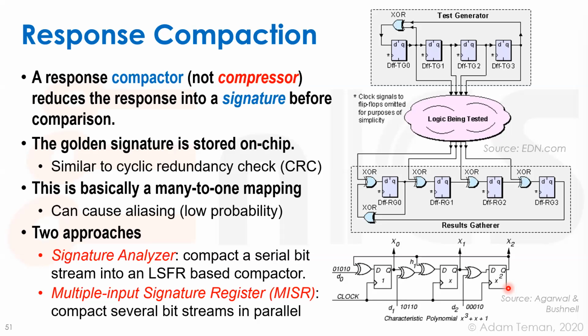Again, we run this before making our chip or in simulation. We see, if we put a certain seed inside the LFSR, we know what the output will be for our set of tests. So all we have to do is store that output and check that the state of the MISR at the end of the run is the same as what we stored. And we don't have to store very much, so it's really good. Okay. Any questions about that? It's actually very cool.